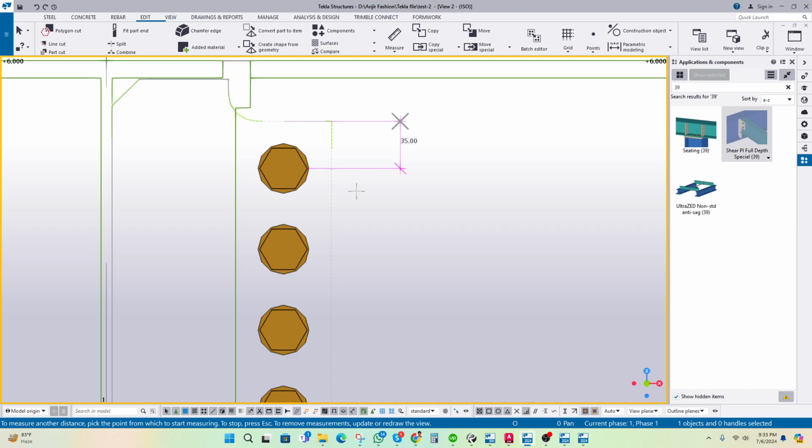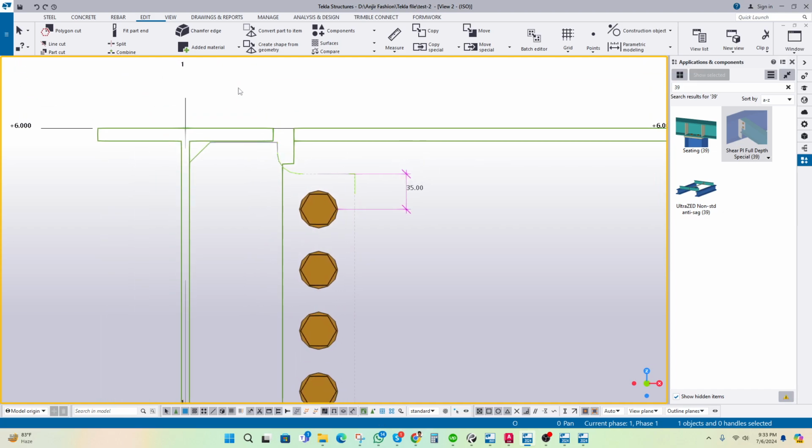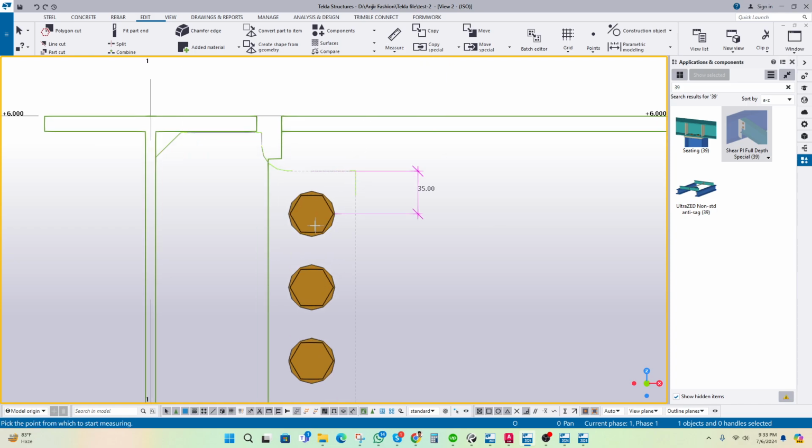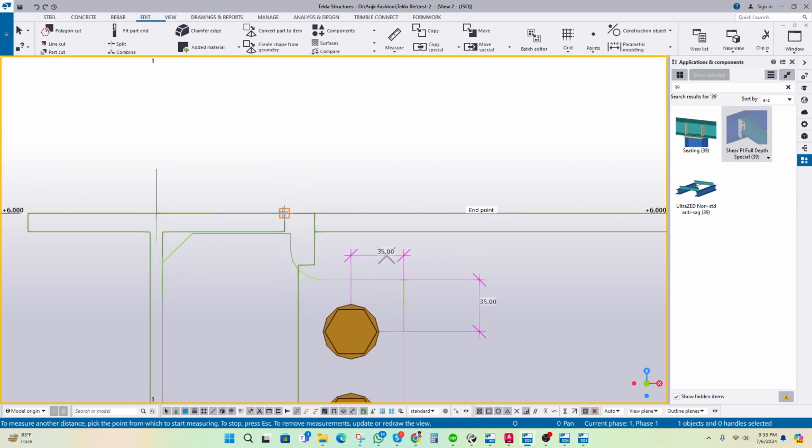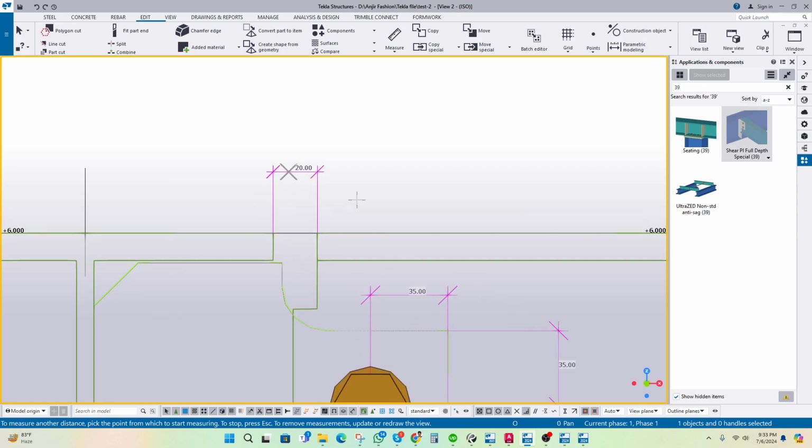When you see that here it is not 35, for example here it is coming 20, that means it does not maintain the AISC code or the European code, right? So at this time you have to know the minimum detailing standard. Check from here to here how much, and check with your sheet what the designer is providing, or what the standard is for the edge distance of the bolts. For example, here we provide 20 mm.